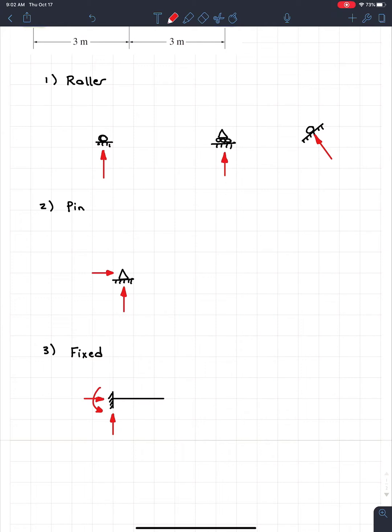They can be. But what happens in an actual building is there are going to be lots of support reactions, millions even. And for that case, we're going to have to rely on other methods, because the statics that you guys learn is only for these determinate structures. But as you may have guessed, in structural engineering, we want indeterminate structures. So we want that extra support in case, let's say, one of the columns of a building decides to crack and break. There will be that extra redundancy to help keep the structure up.